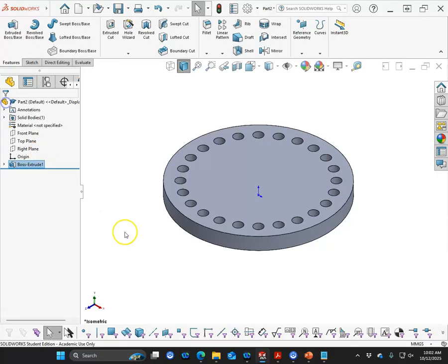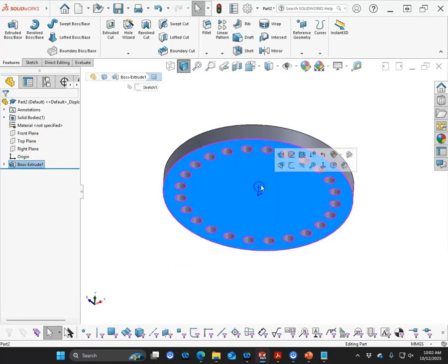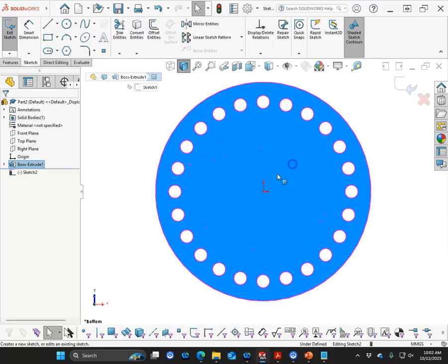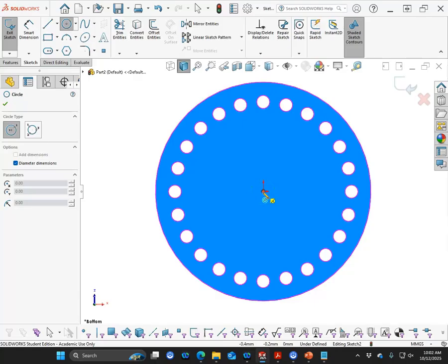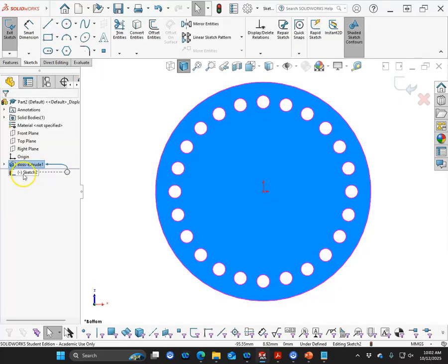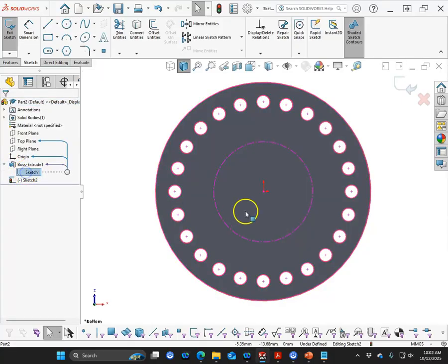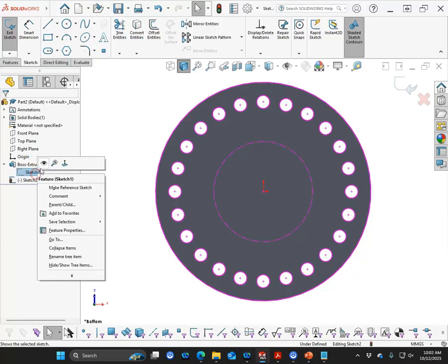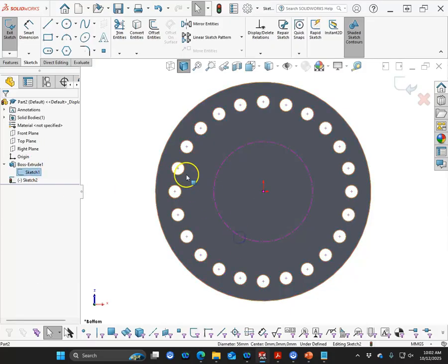All right, because the arcs fall away, I'm going to open up a sketch on the bottom as the center. So let's see, we had also a wall thickness of 11. So let's open up or show the previous sketch so that I can just convert it.